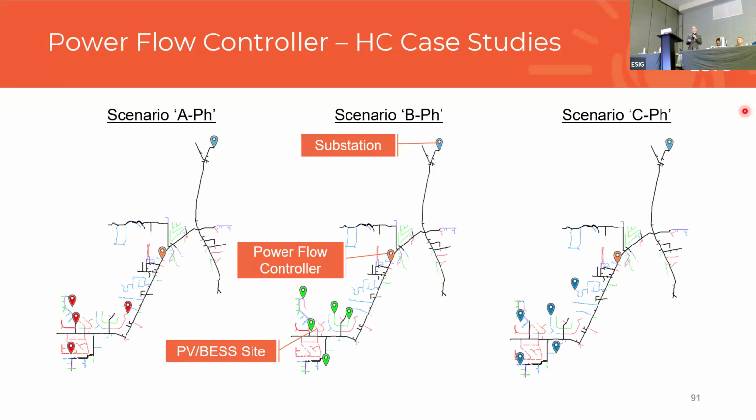So another thing that was done with this particular circuit and pilot was assessing hosting capacity benefits from a PV or an energy storage perspective. And it was more residential adoption of PV or energy storage. So it was, okay, you have these single phase communities, laterals out on a system. If you started to get higher penetration of PV in some of those single phase areas so that it is an unbalanced adoption of these, how would the device perhaps help with this? Because it's going to help both from a load perspective, but also a generation perspective.